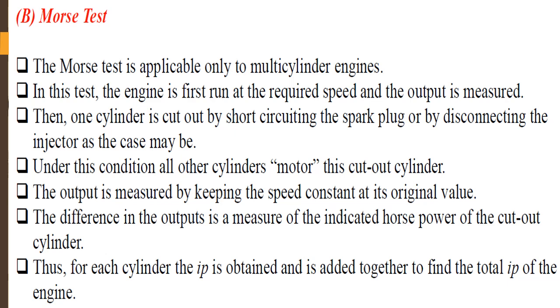So now we will go with the next part, that is the Morse test. What you will observe is that this Morse test is applicable only for a multi-cylinder engine. This is a very important thing. The question may come in a competitive exam, in an MCQ: if it is a single cylinder engine, is it possible to go for the Morse test? No, it is not possible. So the Morse test is applicable only for a multi-cylinder engine.